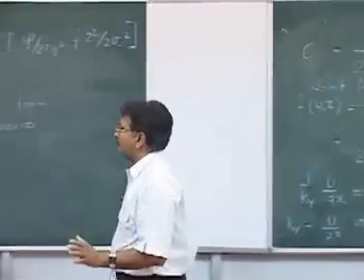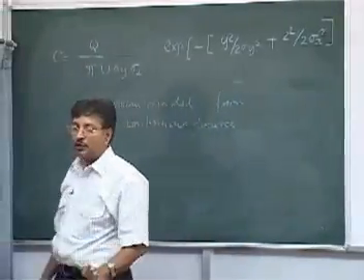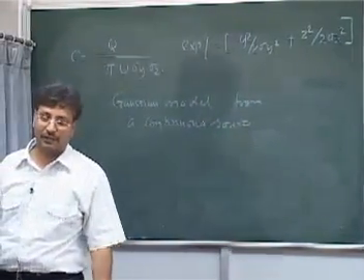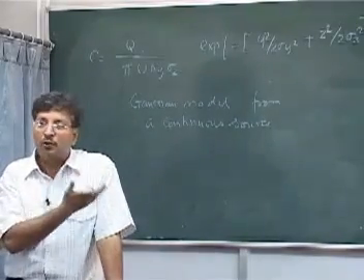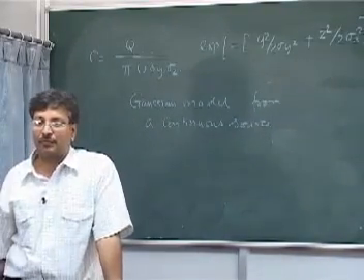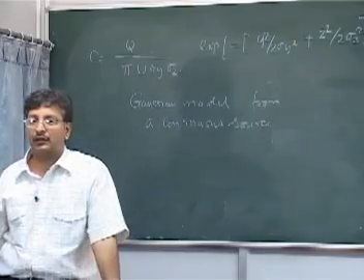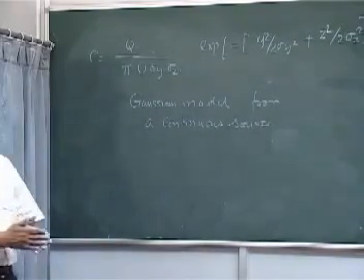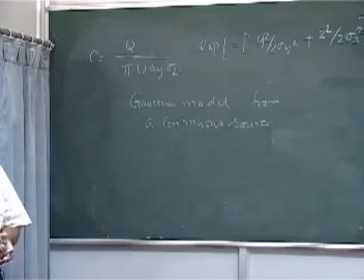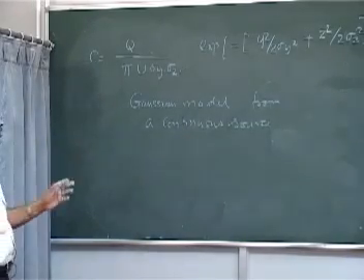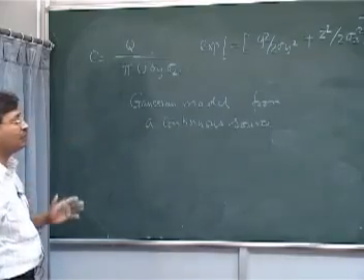Somebody very quickly tell me what will be the units of sigma y and sigma z. Because dimensionally this is an analytical solution, the units must match. Units of sigma y and sigma z. Meters, length units, good. And we'll go a little more into this, explaining a few things.